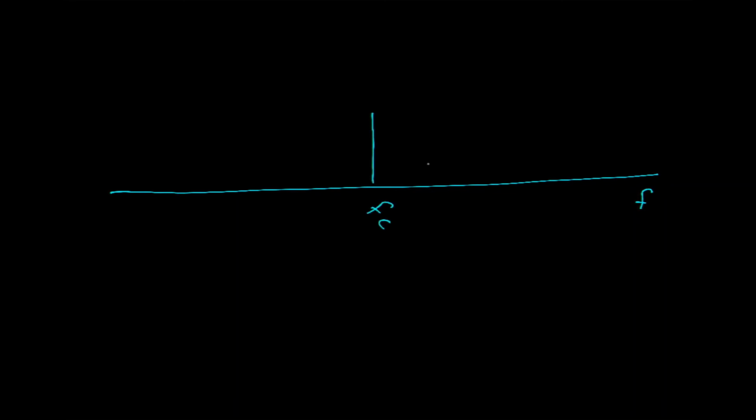Back to the drawing board. In the frequency domain, we have the carrier, the first sideband pair at FC plus the modulating frequency and FC minus the modulating frequency. And that should look familiar. That's what we had in AM. But with FM, we add additional sideband pairs.